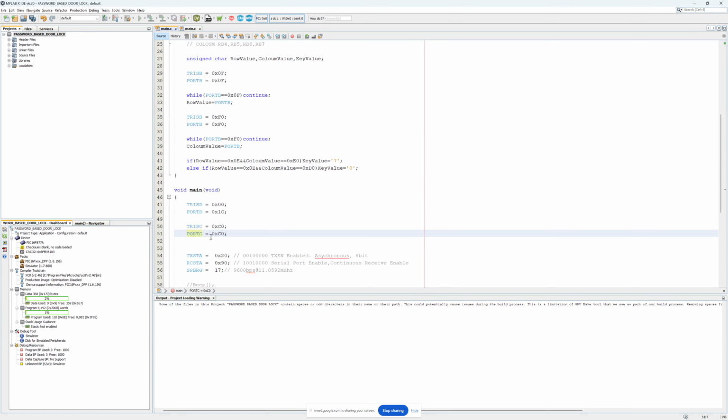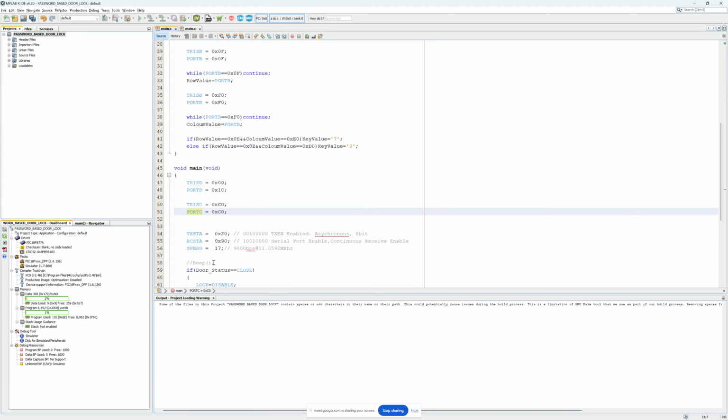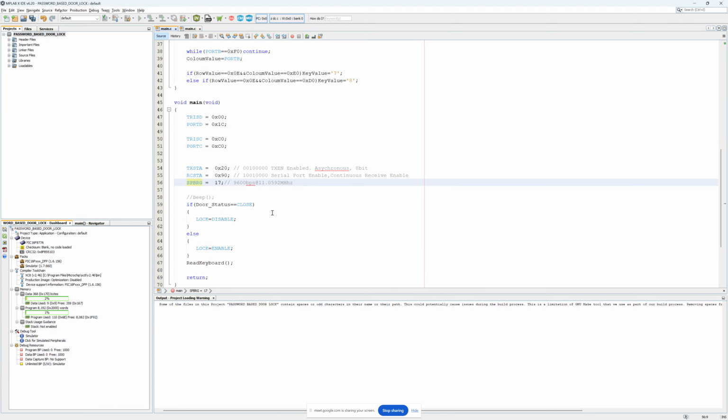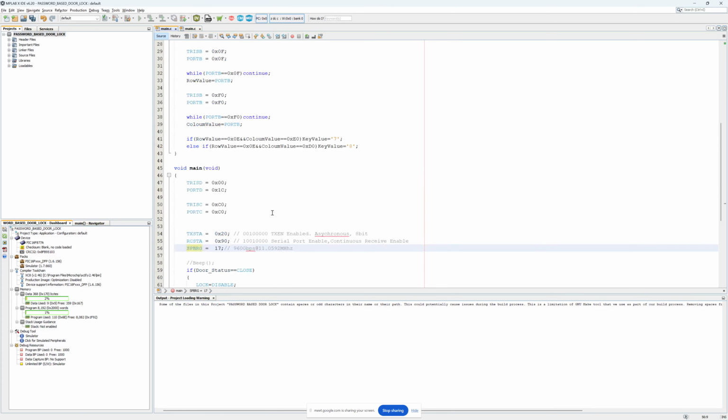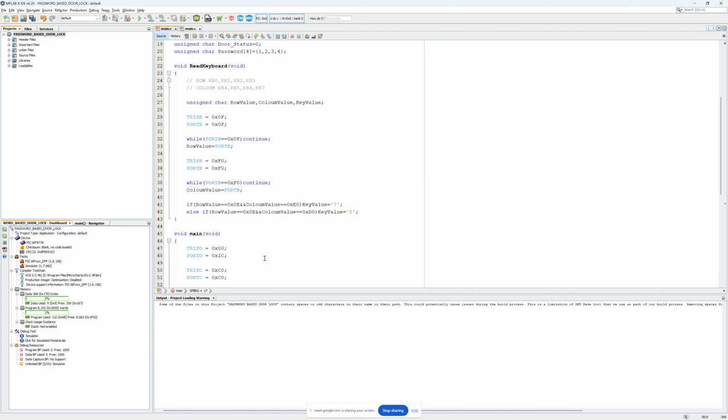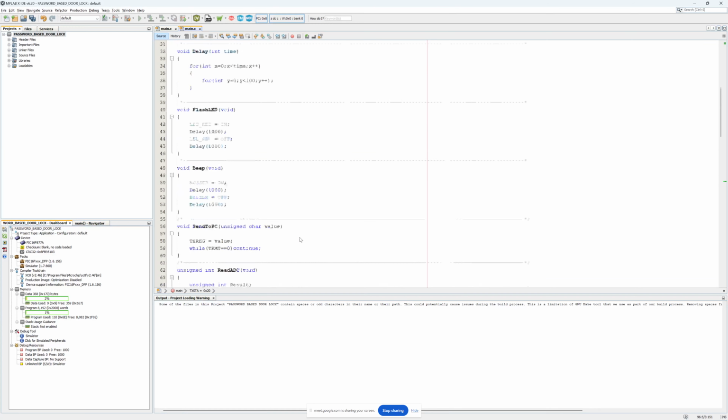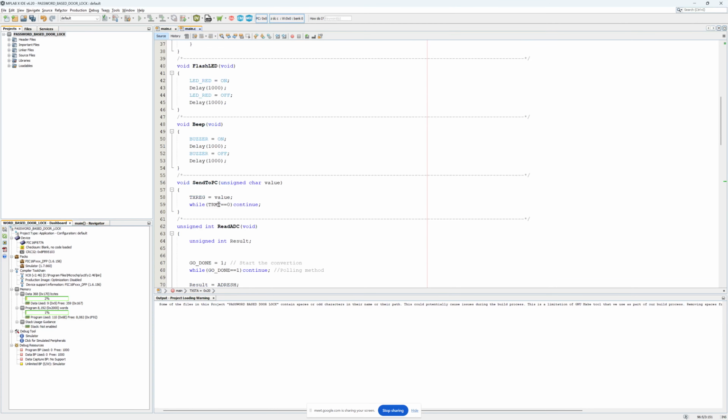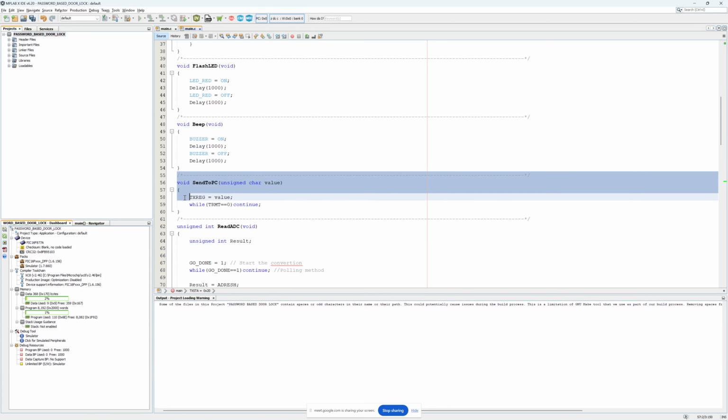Also, we can make port C's RC7 and RC6 pins high state. After that, we configured the UART communication related registers, TXSTA and RCSTA. Then we configured the baud rate at 9600. Now we can check our UART by writing a value to the UART peripheral. For that we wrote a code last week. This is that code.